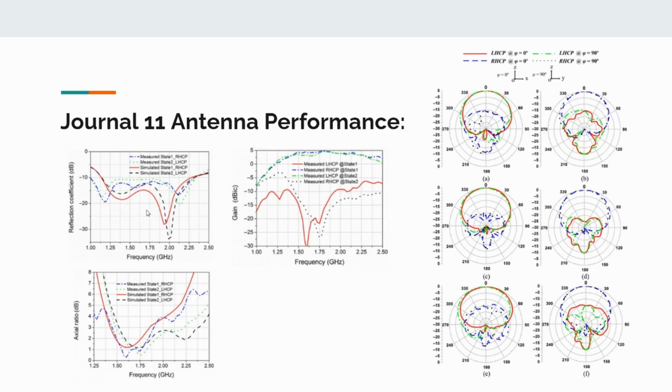So next, we see the axial ratio. The axial ratio exhibits the measured and simulated AR bandwidth for both modes. The simulated and the measured results are in good agreement. The values of CP, co-pol, and cross-pol will change simultaneously according to the impedance. Therefore, the AR bandwidth is not affected by this discrepancy in impedance matching.